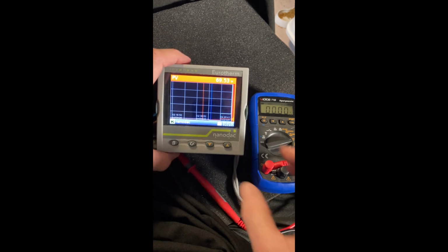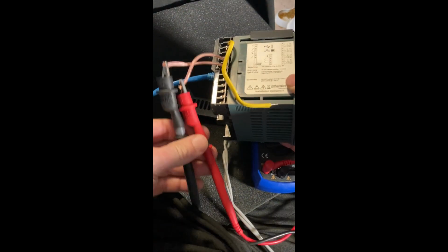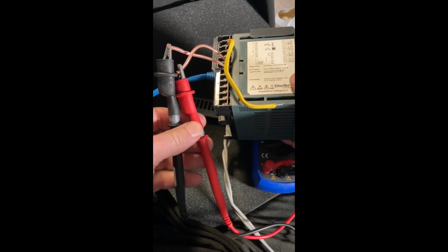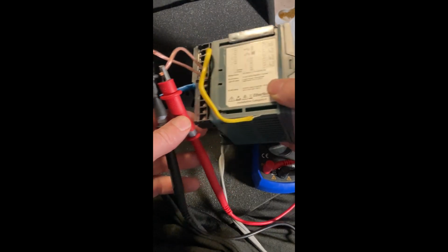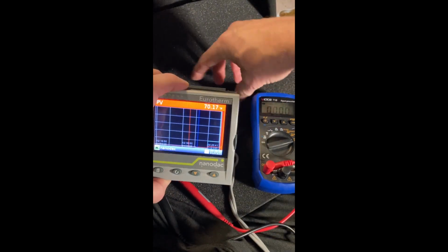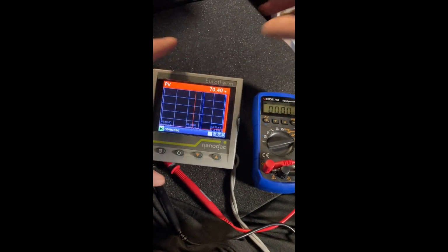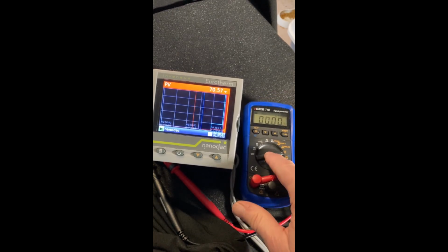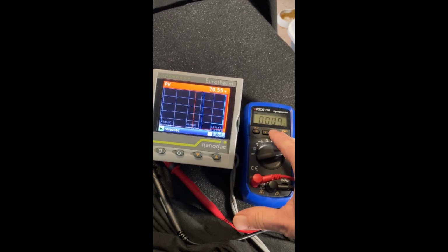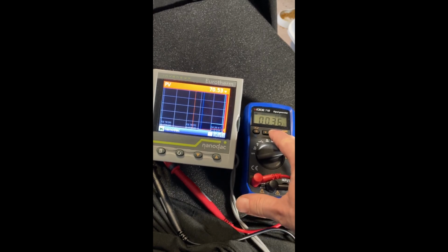So from a hardware setup, I've got a signal generator, and I'm pushing a 0 to 10 volt signal into input 2. So that's the hardware. Again, you can use a 4 to 20 as well. My signal generator is set up for voltage, so I'm going to feed in 2 volts here, and then we'll scale that so we have some results on the nanodac. So let's just put in 1 volt for now.